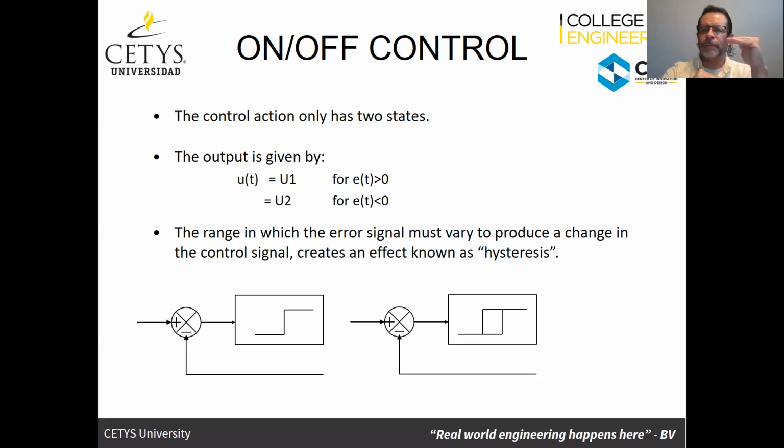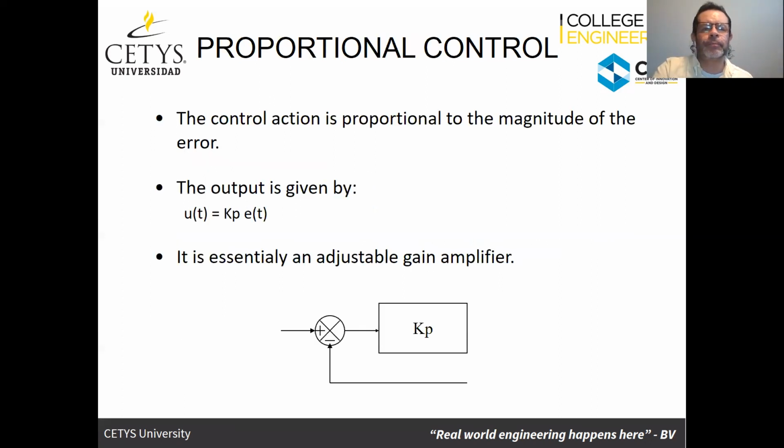So it's going to turn off, and then it's going to go up again. And when it reaches a certain value, maybe plus or minus the threshold, it's going to turn on again. And so that threshold is what we established to go around this hysteresis effect. So the on-off control is before the proportional control, it's probably the most simple control that exists.